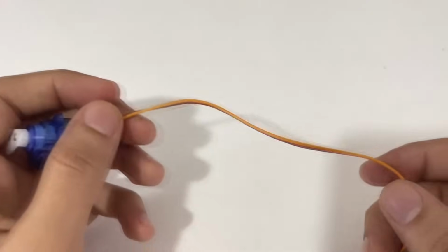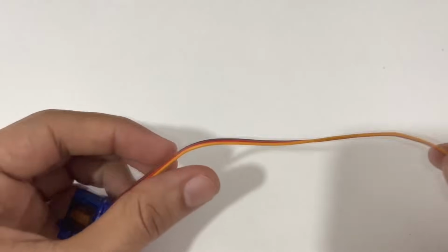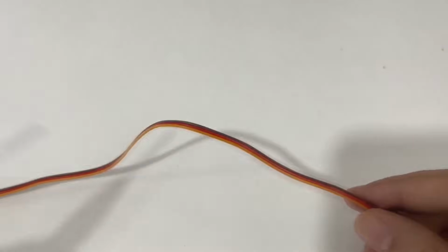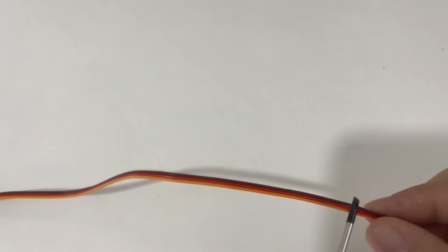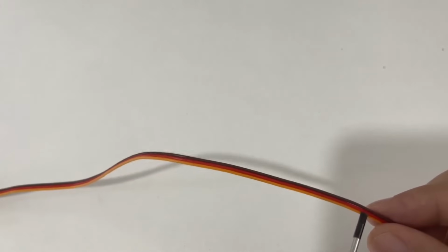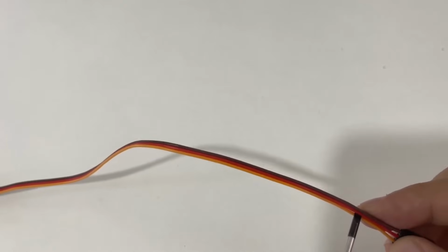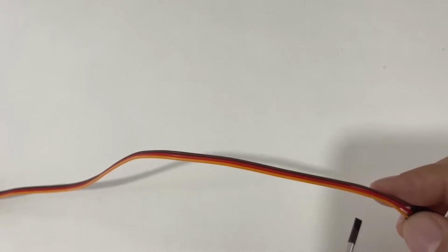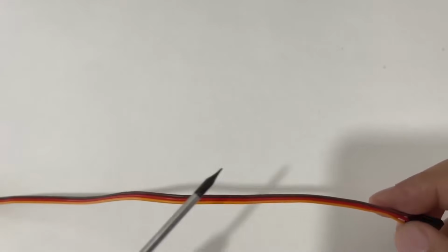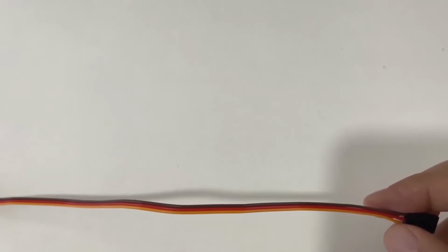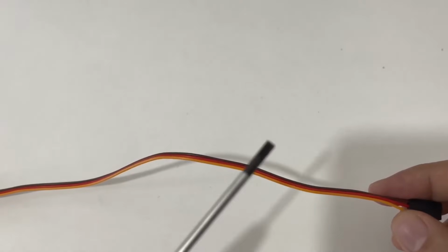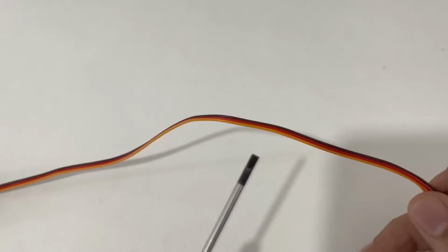Alright, we generally have 3 different lines in our servo motor. You see, the brown line is the ground line. So here is our ground line. And also the red is the 5 voltage line. So here, this is the middle line. And also the orange is our signal line. Together with Arduino, we can control our servo motor angularly. So now let's make our connection first and get our codes ready for use with Arduino. So let's get started.